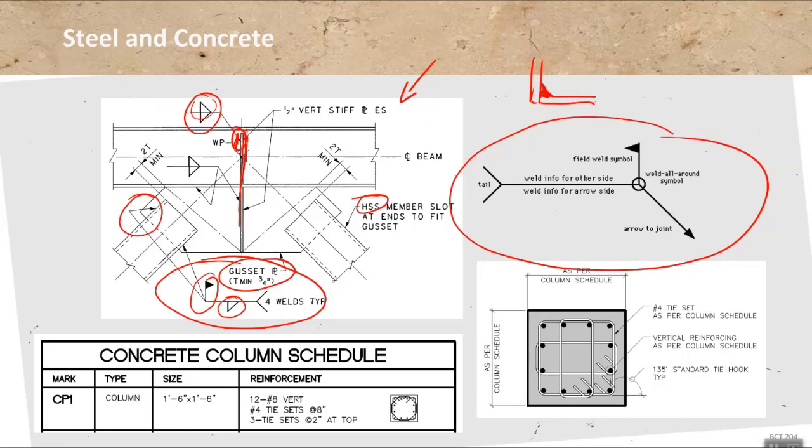For concrete, rebar is the magic juice, and so then of course we need to understand what goes in where. And typically you'll see what you see there on the bottom right, which is a typical column detail where then the arrangement of the rebar is called out, and maybe the ties are called out. But then for the specific individual column, you may find that in a schedule, as you can see here. So this particular column with that size uses that rebar.